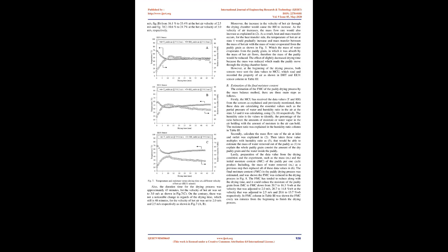During the drying process, 2 sensors were used to read and record the temperature, T, and relative humidity, RH, values of the dryer. Both sensors recorded measured values of T and RH at intervals of 1 minute throughout the drying process. The temperature is read on the left axis and the right axis displays the relative humidity. Fig 6 is a graphical representation of the measured values for the DHT22 sensor. The upper line shows the T of ambient air and the lower line shows the RH of ambient air that was consistent throughout the experiment.